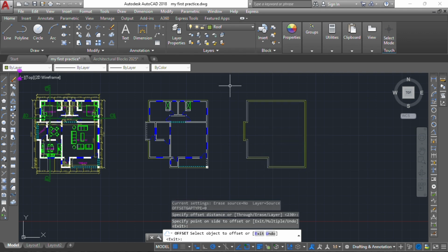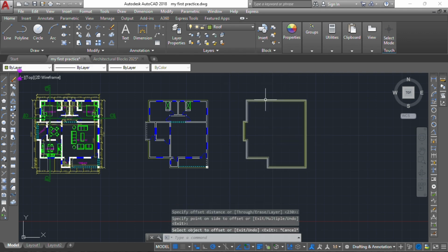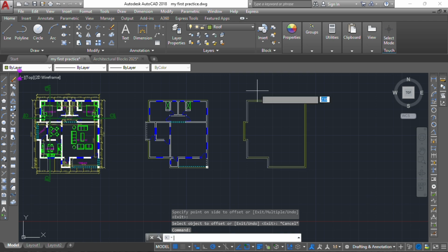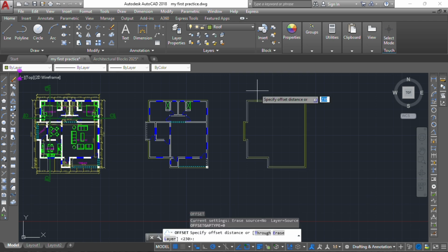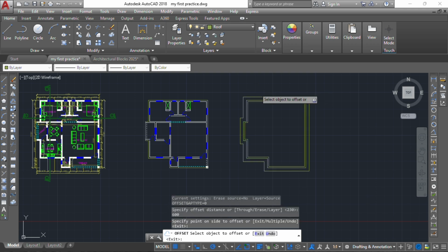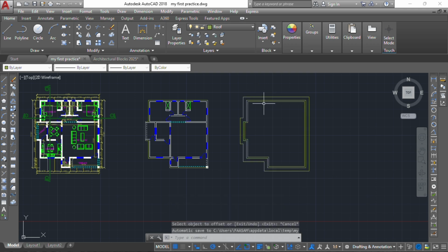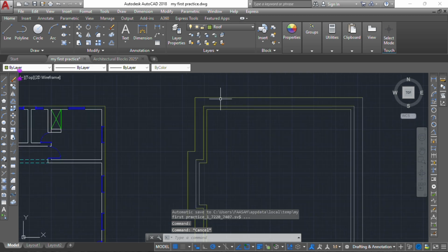and good to go. And I'll offset this outside again for my eaves, which I can use between 450 to 600, right? So let me just go with 600 and leave it like that. Okay. So here now, this is where my roof is starting from.